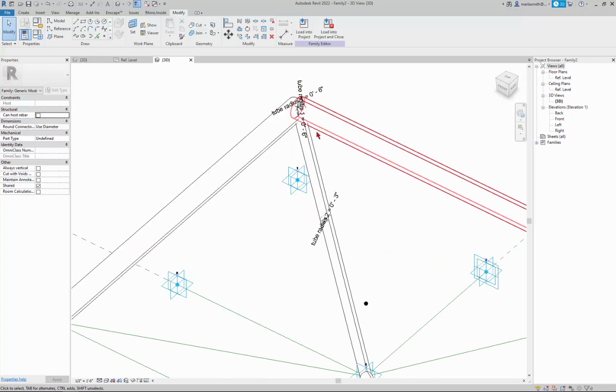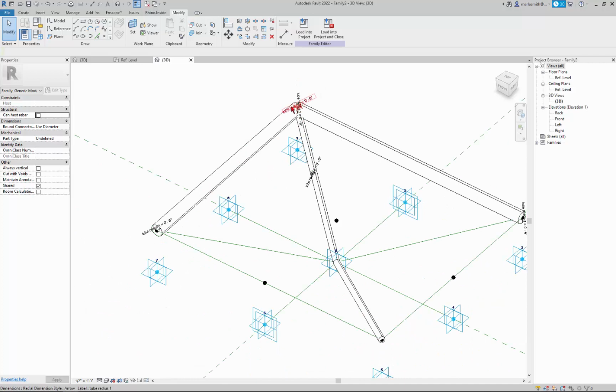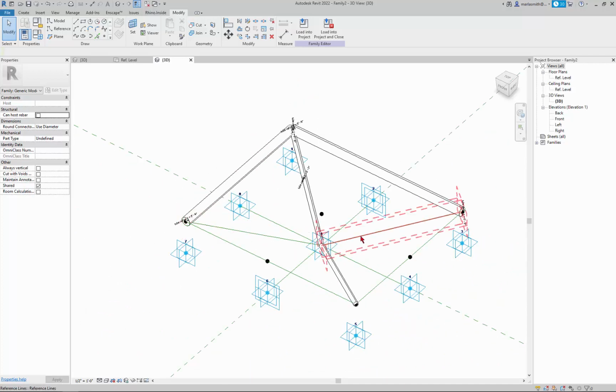I'm not worried about the corners here because we're going to put little balls on there for joints, so the fact that they aren't that pretty is actually okay. All right, I'm going to go through and do the rest of these guys. Again, the ones that are a single line, like this one, you'll have to put 2 on, but if you're picking 2 individual lines, it will sweep it and it will work.